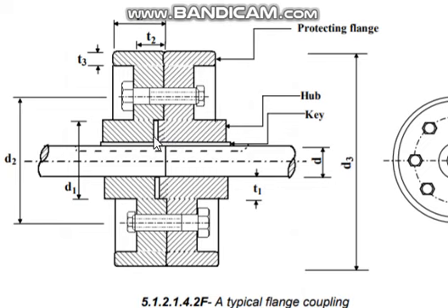Okay, otherwise these holes will not be matching. You will have to struggle to bring them to alignment. So that's why one has a recess, one has a projection, so there may be a little gap between them. Otherwise, if the gap is more, then the gap will remain throughout. Okay, then there are nut bolts here, two nut bolts are there. There can be any number.